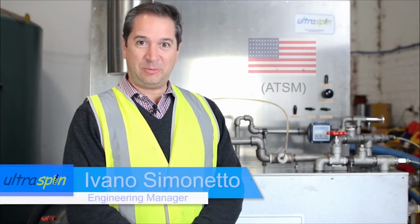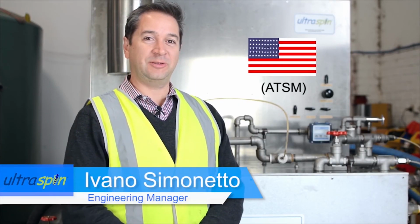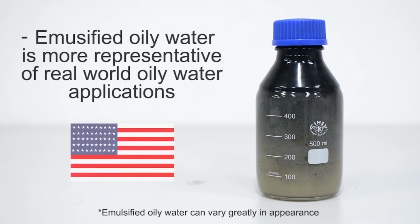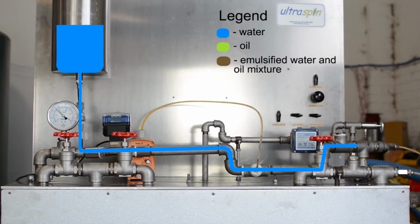For most industrial applications, the ASTM series of testing methods is used. The most important difference between the American standard and the European standard is that the American standard intimately mixes the oil into the water to create an emulsified mixture. We first dose a known amount of oil into the water, where at this point here the oil gets injected. Here the oil is mixed into the water by a mixer, and the emulsified oily water is sent through to the oily water separator, where it is separated.